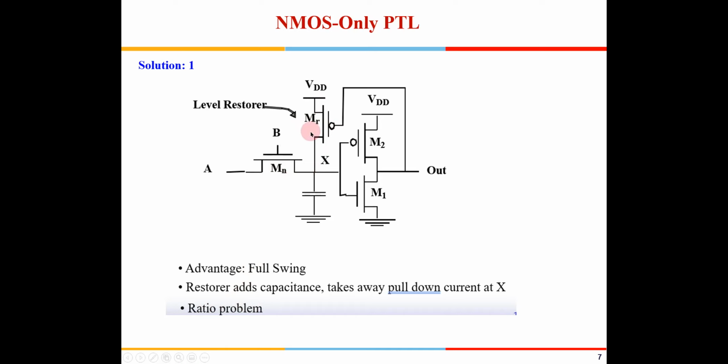This becomes a kind of ratioed logic. Unless this transistor is able to draw large currents, the switching won't start. But once this switching happens, this becomes 0 out here, this will become 1 and this will get switched on. But that initial force which is required has to be catered for by keeping this size larger. So how are the transistor sizes calculated?